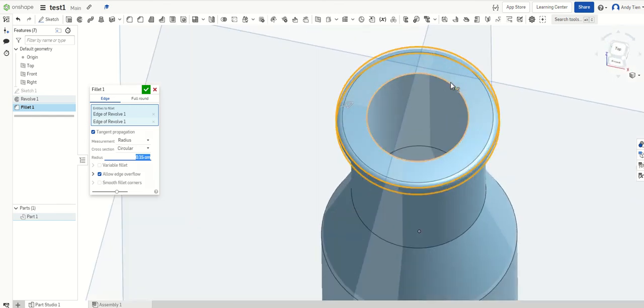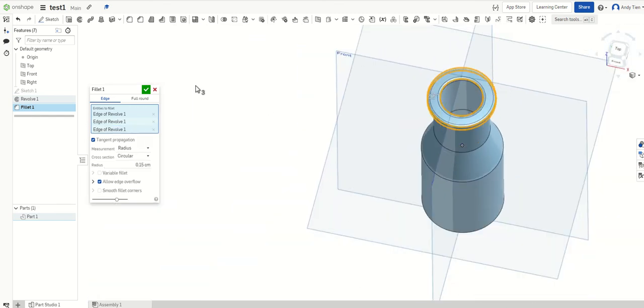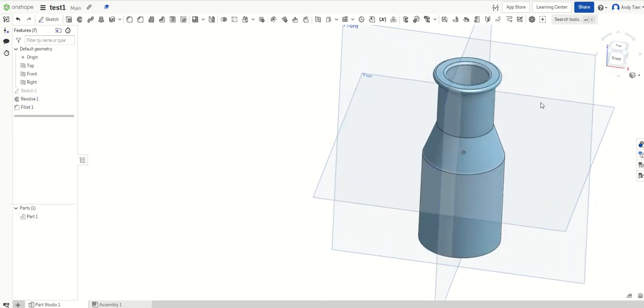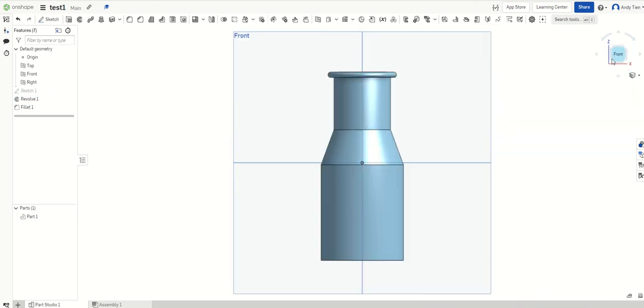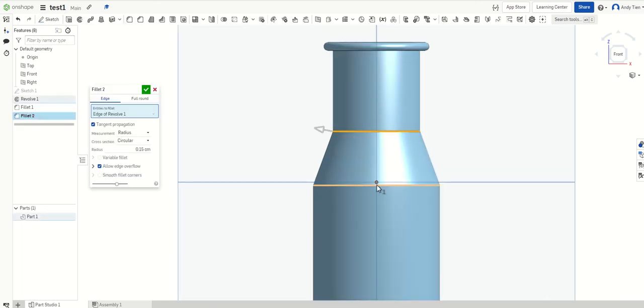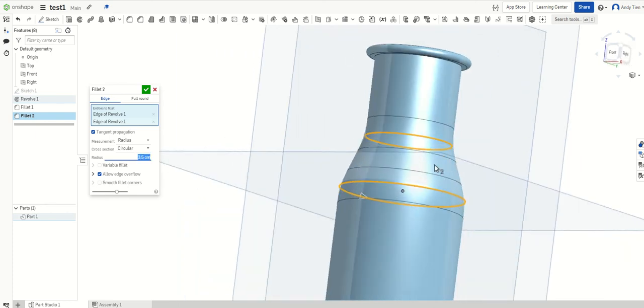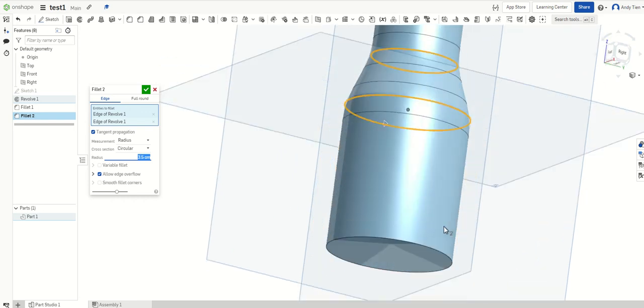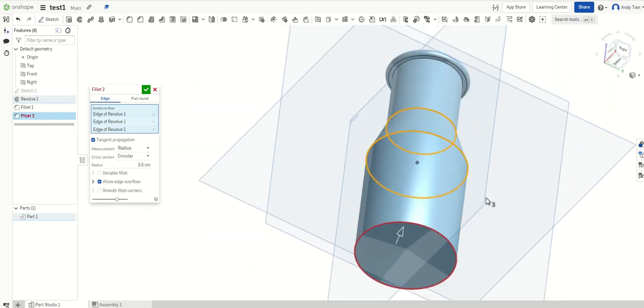And I'm going to do the same for the inside because it looks cooler. Okay, and then moving on, you can see all these edges are really rough and not very beautiful, if I do say so myself. So after this is done, I'm going to fillet these edges, right? So once again, you take your fillet here and here, and we're going to make it 3.5 centimeters. So it has a nice gentle curve. Also, don't forget the bottom edge, because that needs to look beautiful too.